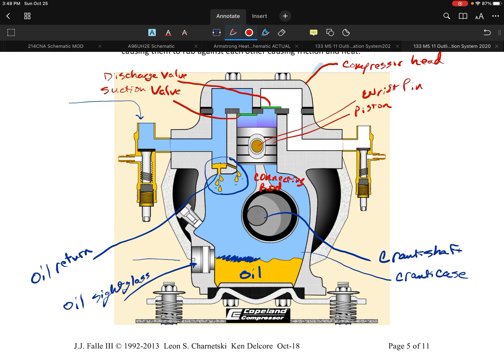Just like we showed earlier, what opens up the discharge valve? Having a pressure difference, a differential. That was one key thing. Suction valve, what opened it? A differential. What opens the discharge valve? A differential. So that's the skinny on there. If you look at this image, you'll see the flow can only move this way. At least that's the way it's supposed to work.